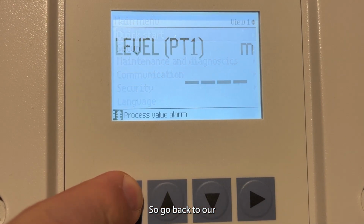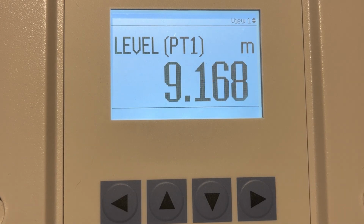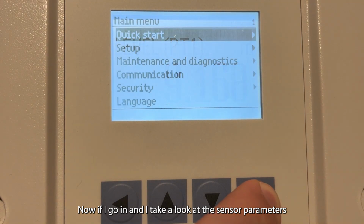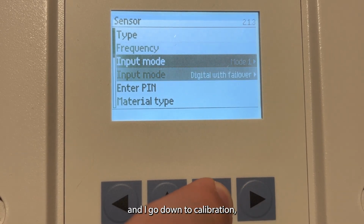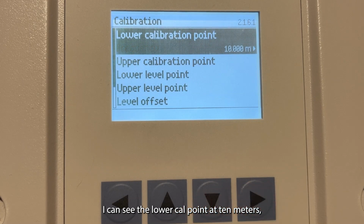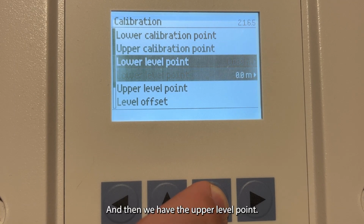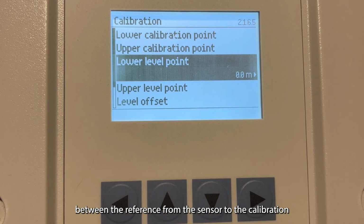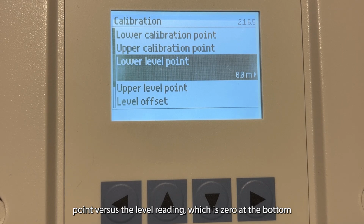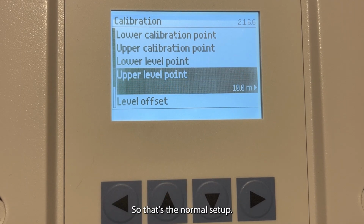So go back to our run screen here. And now we see we're measuring, and we're fairly close to our upper limit. Now, if I go in and take a look at the sensor parameters that we were just looking at in our diagram, and I go down to calibration, I can see the lower cal point at 10 meters, just like we set up, the upper cal point at 0, like we just set up. And then we have the upper level point. So again, that's the reverse of our calibration points, because we're looking at the difference between the reference from the sensor to the calibration point versus the level reading, which is 0 at the bottom and then 10 meters at full capacity. So that's the normal setup.